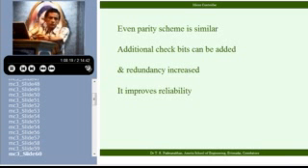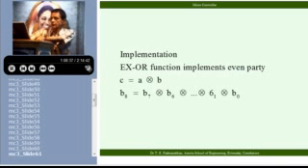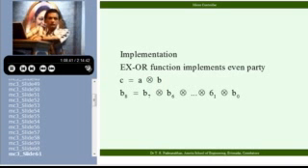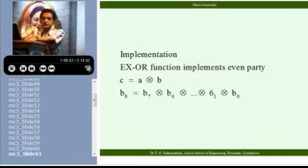Now you can build upon the logic, and instead of putting one parity bit, you can put 2, 3 parity bits and make the data more redundant. Of course, these are all dealt with in very great detail in data transmission schemes. I think we'll just leave it there. You put more and more bits and make it more reliable. Now, coming back here, the process of doing parity checking is done by putting exclusive OR gates. You can check upon that.